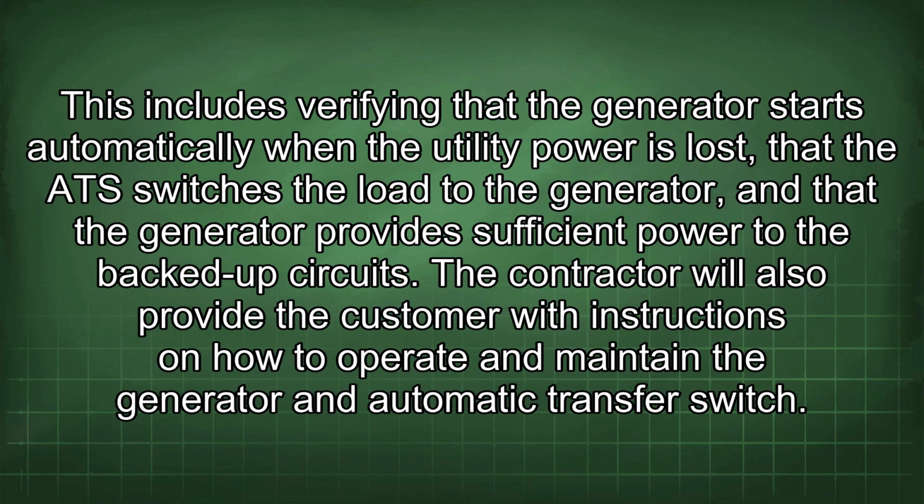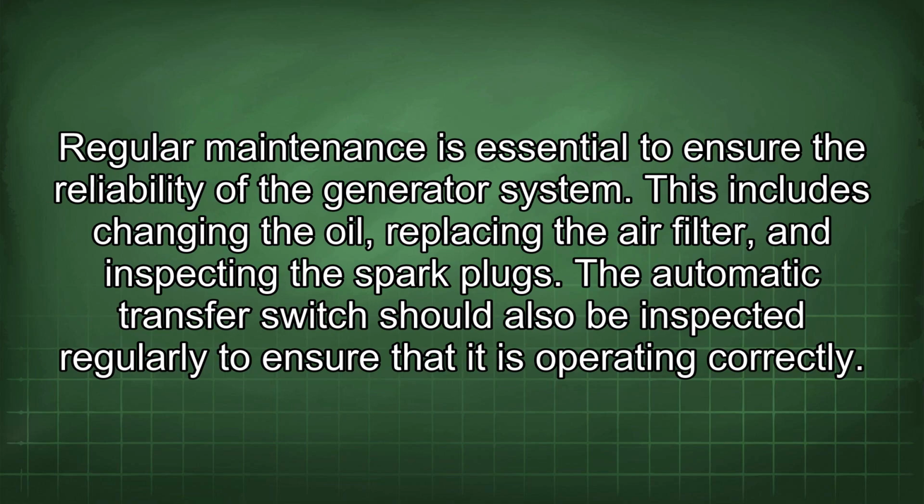The contractor will also provide the customer with instructions on how to operate and maintain the generator and automatic transfer switch. Regular maintenance is essential to ensure the reliability of the generator system. This includes changing the oil, replacing the air filter, and inspecting the spark plugs. The automatic transfer switch should also be inspected regularly to ensure that it is operating correctly.